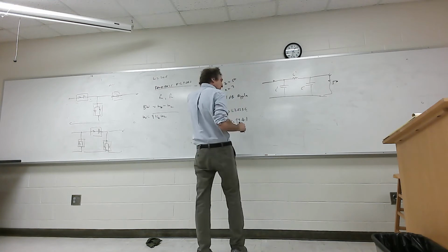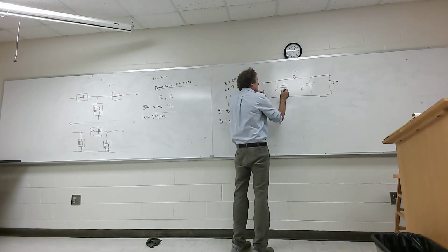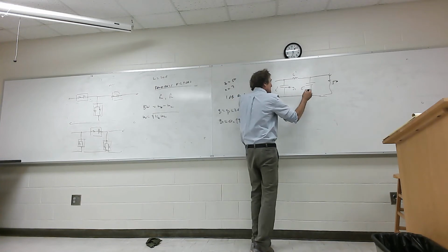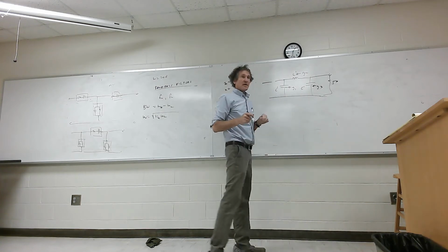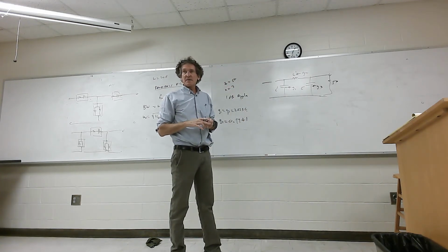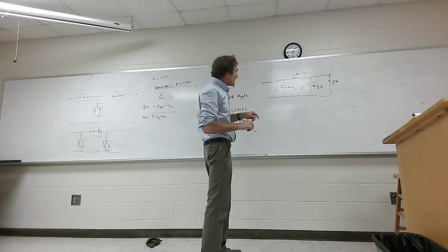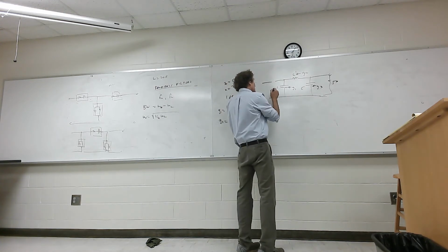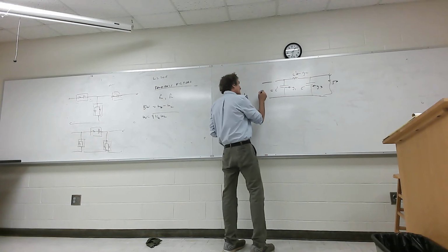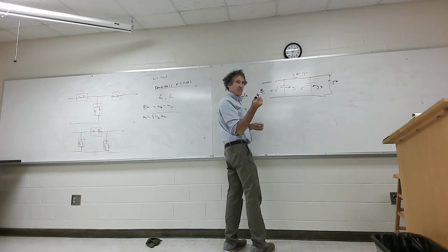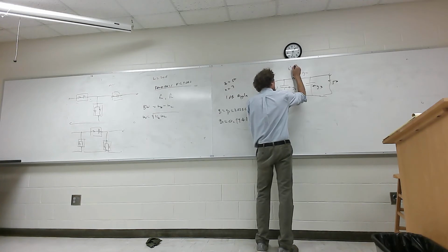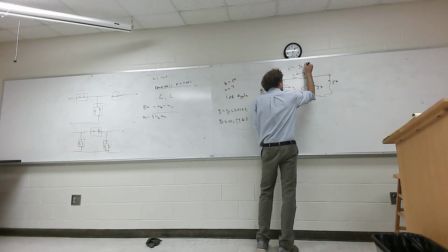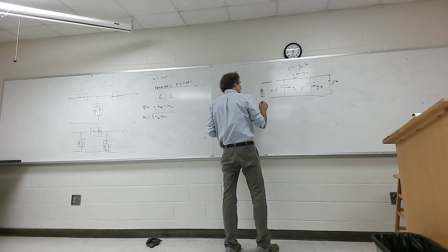All right, now remember, this is associated with G1, this with G3, and this with G2. You all remember that? So first we get the normalized values. We don't divide them by omega C. So how do you get this C prime? It would be G1 divided by Z0, correct, everyone? L prime is going to be G2 times Z0. And can you give me this value for C prime right here?